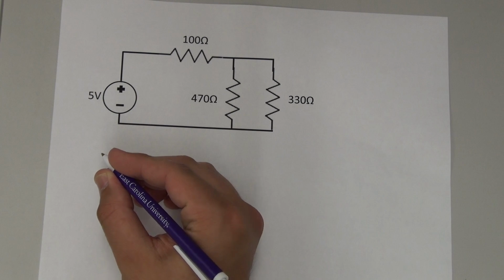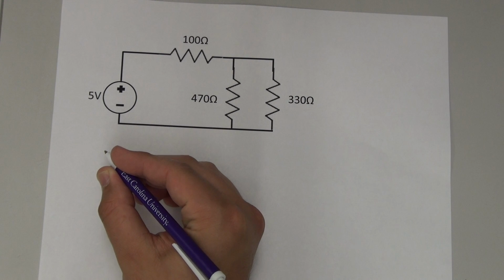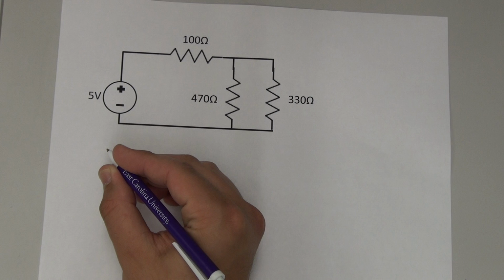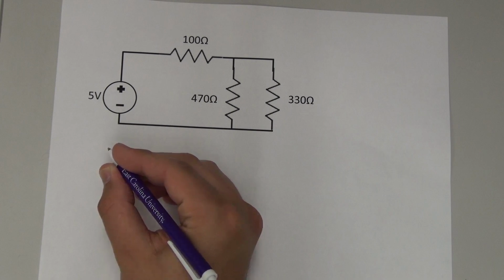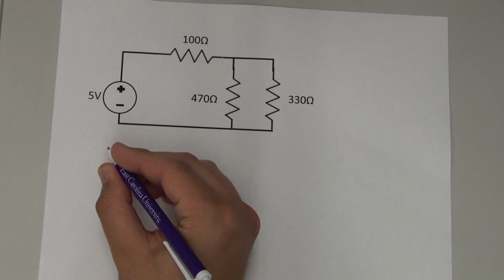In this video, I will introduce basic circuit analysis to analyze a simple resistor-based DC circuit. This is part 1 of 2. In this part, we will determine what the theoretical currents and voltages should be through and across 3 resistors in a series and parallel network. In part 2, we will assemble the circuit and we will see how the measured voltages and currents compare to our analytical solution. To begin, let's first look at how we could analyze this circuit.